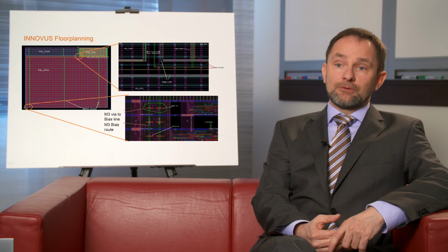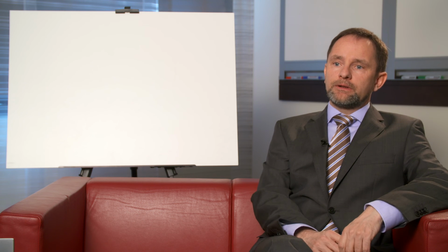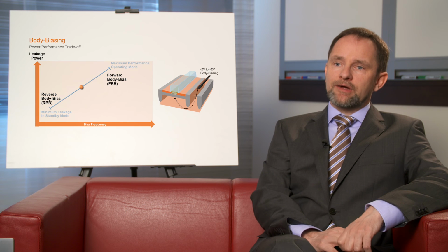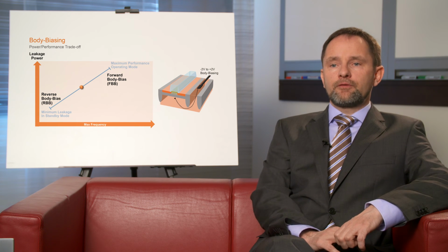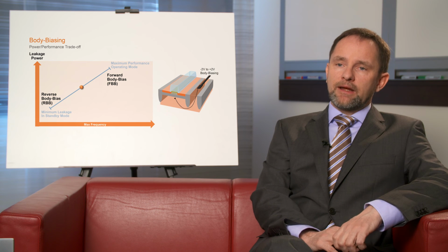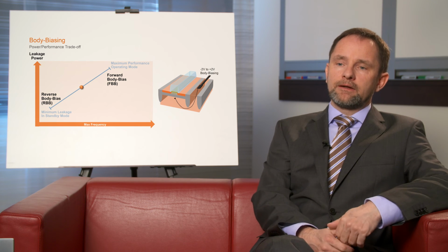So this is one of the challenges, but with the reference flow GlobalFoundries has put together, we are showcasing that in our design example, and for the customer it's really then just repeating what we have done in our design example. From this project we have demonstrated in the reference flow example that when you time a design at different bias voltages, you can see immediately in the place and route tool and in the power reporting the results.